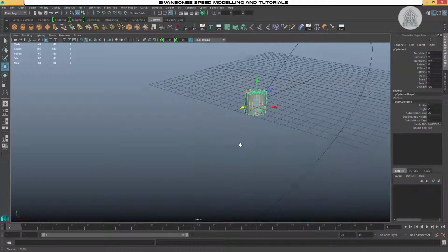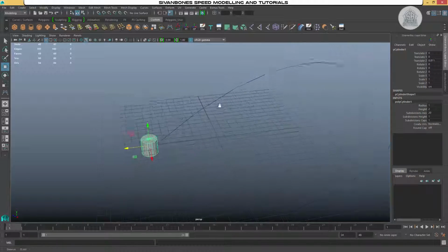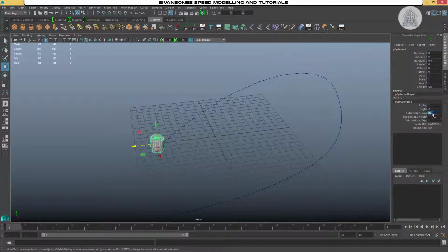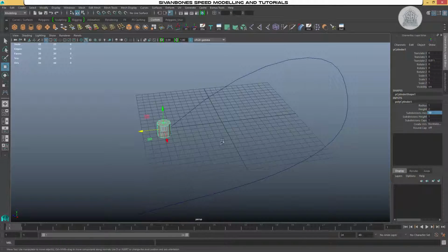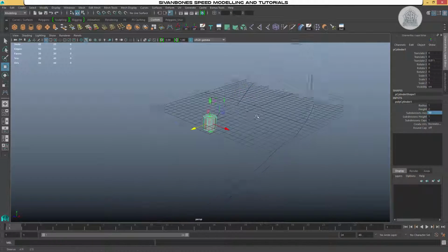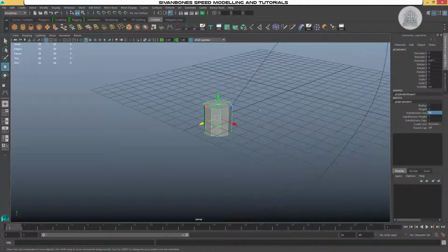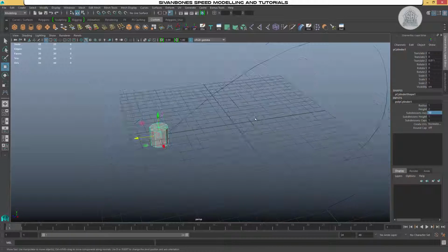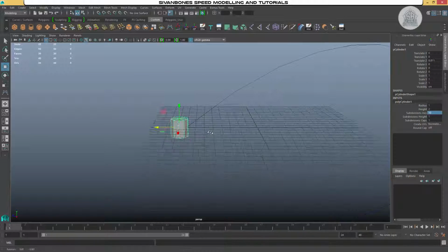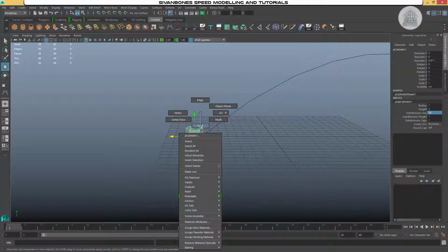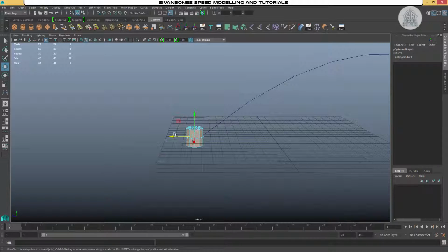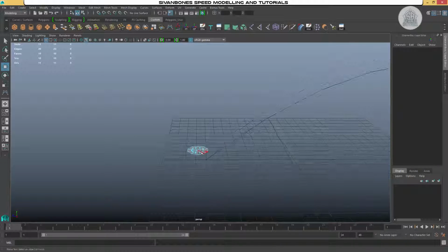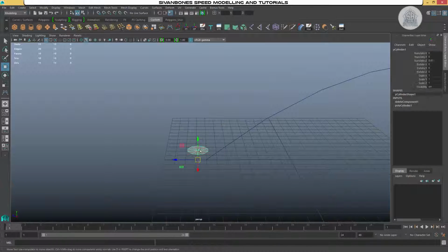Depending on what this is going to be used for, we may need to lower our subdivs, otherwise this one curve will be a very high poly object. So I'll just set it to 10 now, and then we can see how high poly it is after. So what we want to do is go to faces, and delete all the faces so we have one end left.